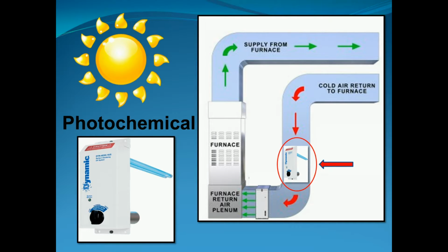So we'll put low levels of ozone inside the duct, so as the gases come through the return, it will hit it with ozone and put it back out into the breathing space. Now we have less odors, less gases, less organic compounds, and virtually no ozone. Yeah, well, I think that goes back to when we have the lightning strikes that occur outdoors. That ozone gets used up pretty quickly.